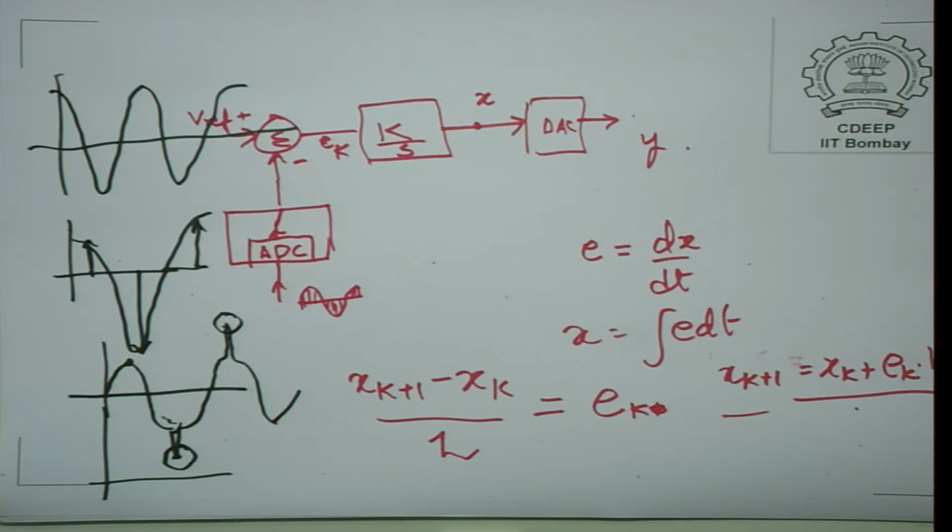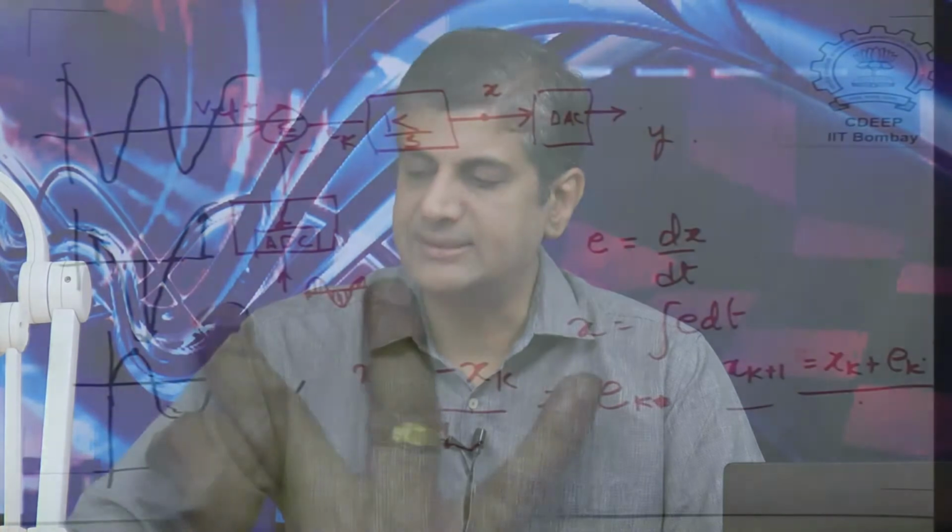So, what we usually do, knowing that I am going to sample at, say, 200 hertz, is make it a point to remove all the frequency components which are higher than 100 hertz. You first remove these spikes and then you sample.